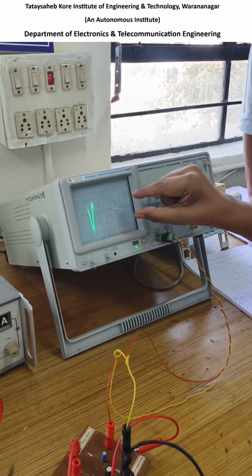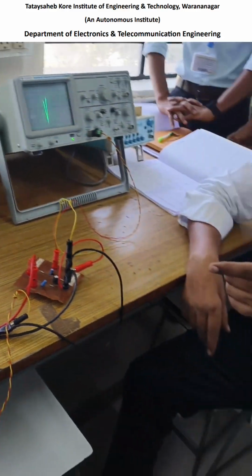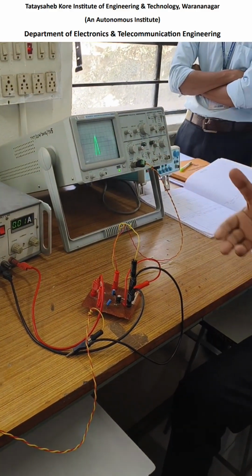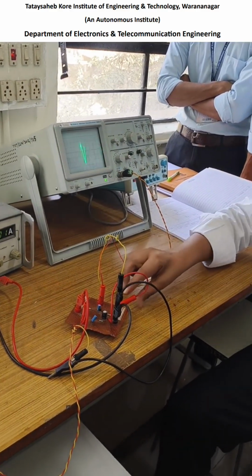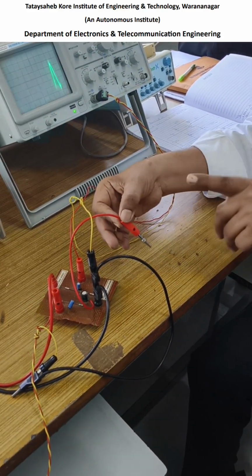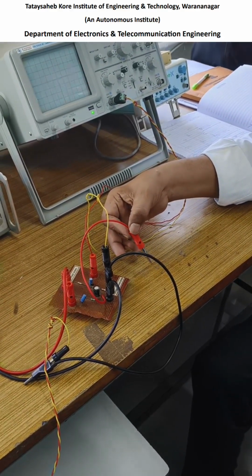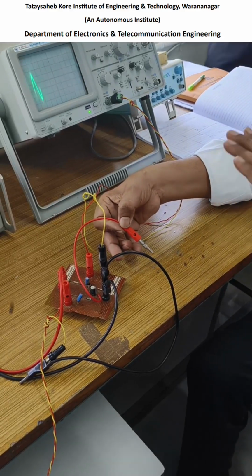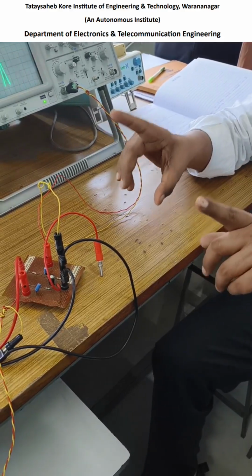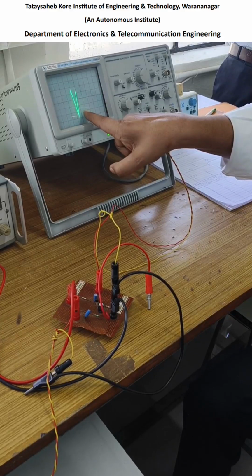Previously, when you measured the voltage at the signal generator, what was the reading at that time? 20 millivolt. But now you check the signal, you will find that the amplitude is increased. Take care that at that time I have not connected this CE. When this is not connected, my first table is amplifier with feedback, because my CE is removed, not connected. So the first observation table which I am completing here is for with feedback. So with feedback, what output am I getting here on the screen, now you check.